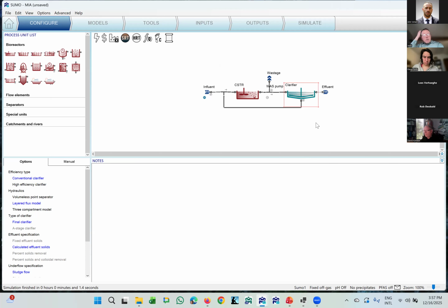We're using 9 layers, and that's coming from the fitting of the numerical diffusion that Elena was talking about. That worked better with 9 than with 10. So unfortunately it's case specific. Otherwise, you would have to introduce a kind of back mixing between the layers to describe this better, which will slow down the simulation even more and add another parameter. So that's another option.